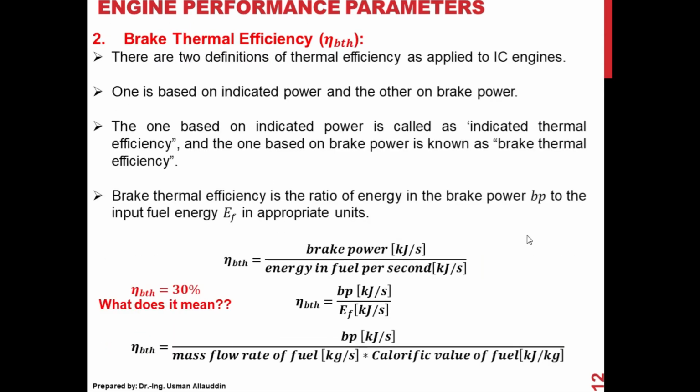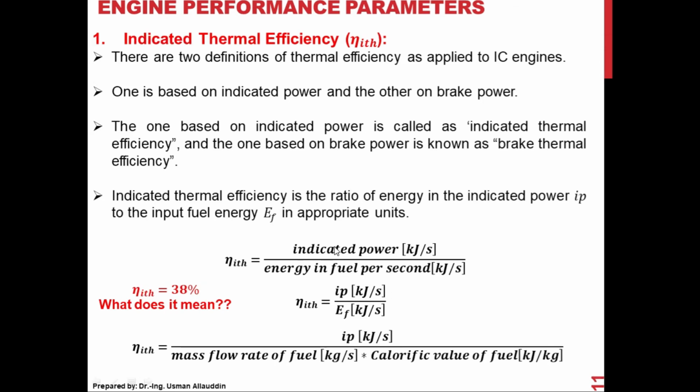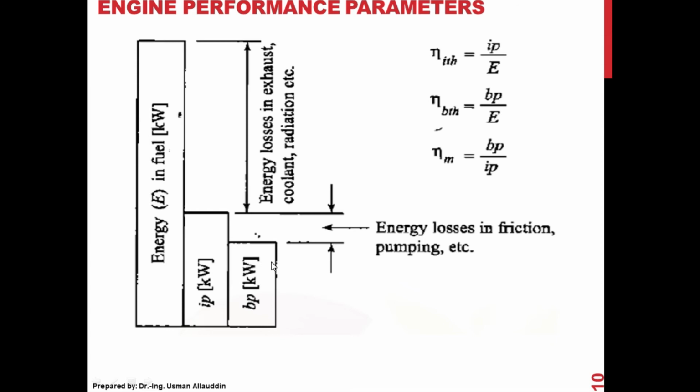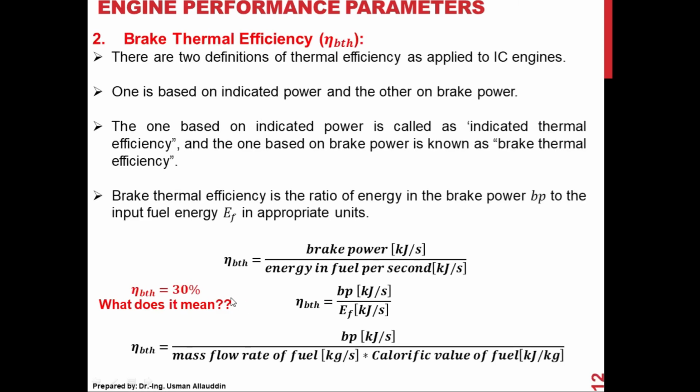It is important to note that brake thermal efficiency is always lower than the indicated thermal efficiency, because brake power has a greater amount of losses. So brake power will always be less than indicated power, and so brake thermal efficiency will always be less than indicated thermal efficiency.